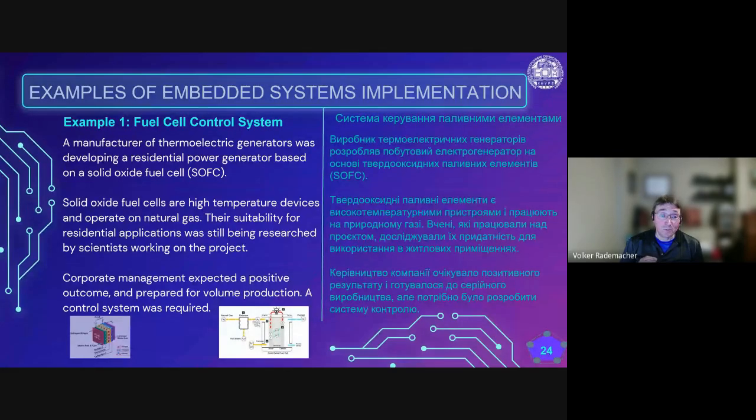A thermocouple is essentially just two pieces of metal exploiting an effect called the Seebeck effect, which means a very, very tiny voltage is generated if two dissimilar metals are connected on both ends, and one end is hot and one end is cold. It is a tiny voltage, millivolts, 25 millivolts, something in that range.